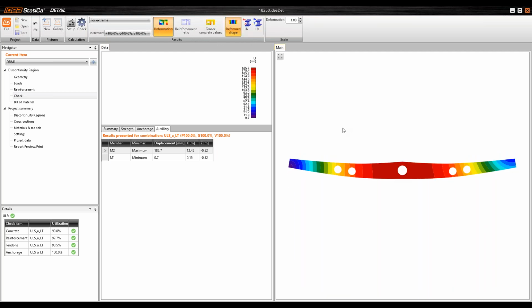So right now, this is a standard design of the pretensioned beam, but if you have a pretensioned beam, there are some construction stages, and you should do the code check in the stage at the pre-stressing.